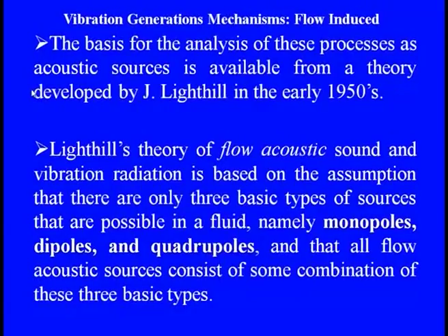Lighthill theory of flow acoustic sound or vibration radiation is based on the assumption that there are only three basic types of sources possible in the fluid: monopoles, dipoles and quadrupoles. All these sources, either separately or in combination, expand in terms of radiation.